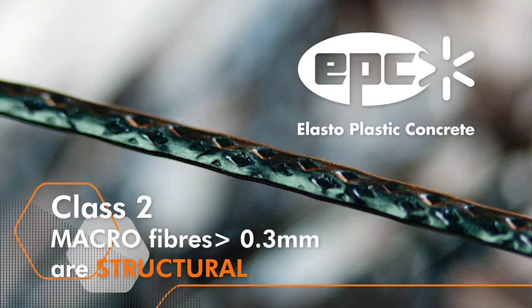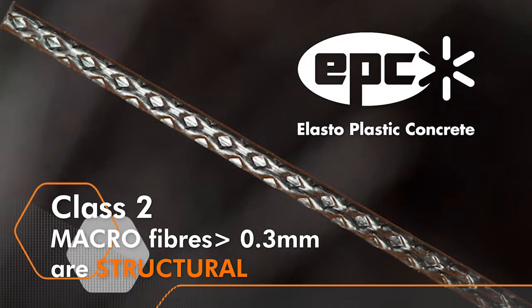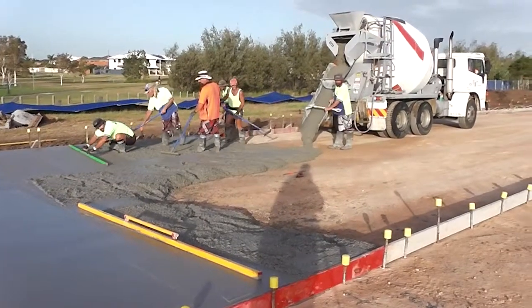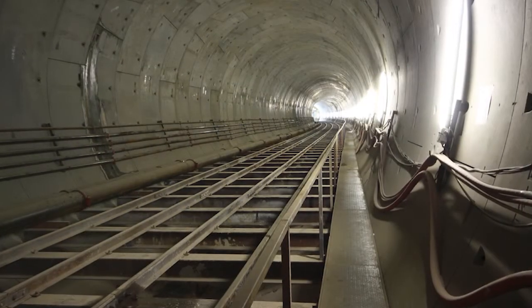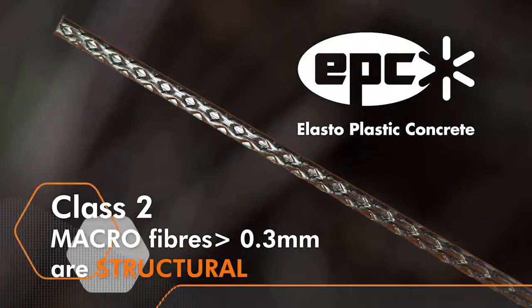EPC's bar chip fibers are a Class 2 structural macro fiber greater than 0.3 millimeters in diameter and can be used to replace crack control mesh or structural reinforcement in concrete or shotcrete. So for structural reinforcing, make sure that you're getting the correctly specified Class 2 macro fiber.